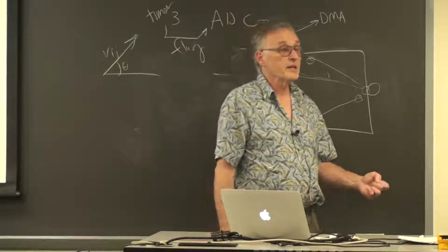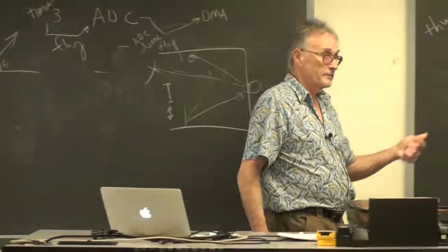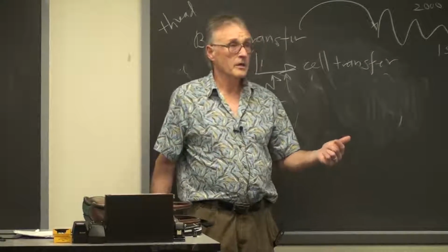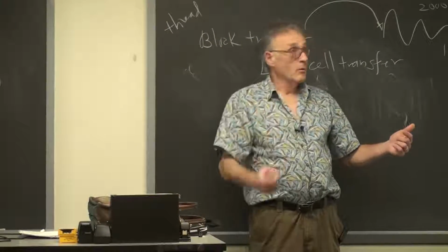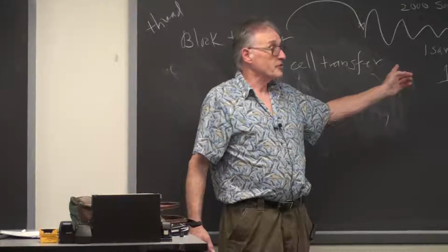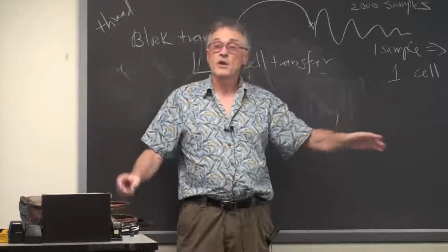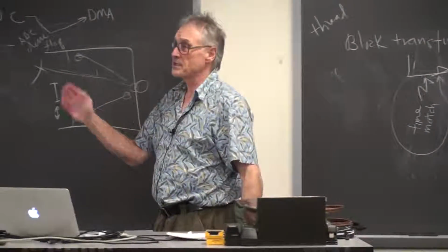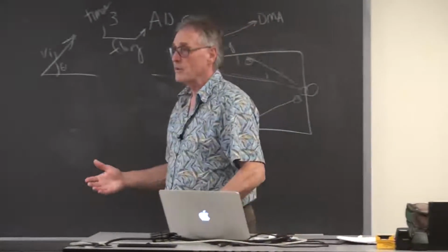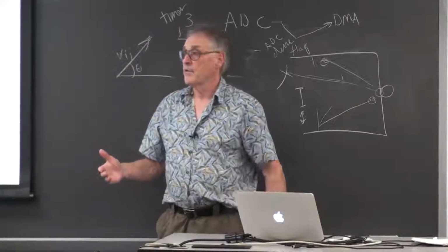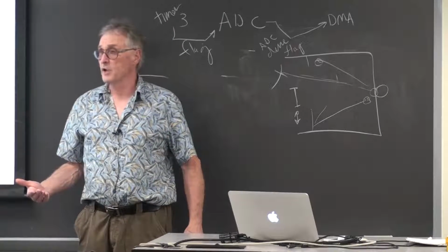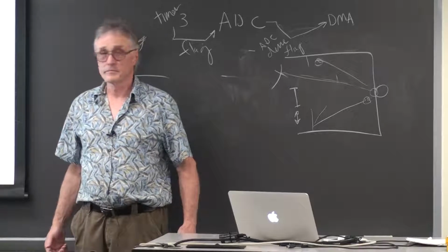So if you start a transfer to the UART as a block transfer of a string, the whole string will be sent with no more software interaction. The UART goes off and sends the data, and when the string is ended, the DMA sends a null. The DMA controller notices the null and aborts the transfer.